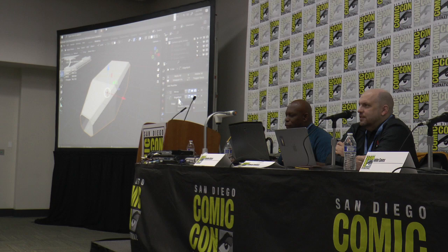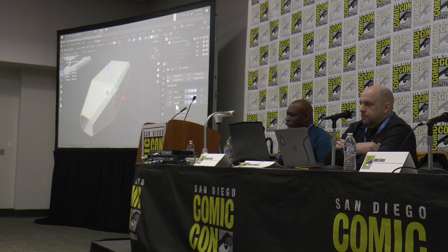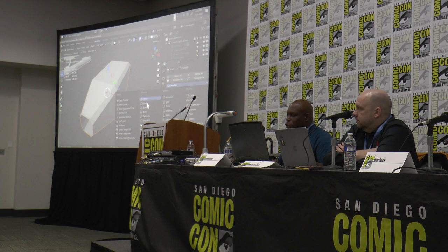The next modifier, you're going to go grab another, is going to be solidify. I'm going to bring it right down here. There we go. So go to solidify. I'm going to cascade that up so we can see them all together. And your final modifier is going to be bevel. There it is. I'm going to put mirror at the bottom because positioning your modifiers makes a difference. So I'm going to drag it, just like layers in Photoshop, drag it to the bottom.